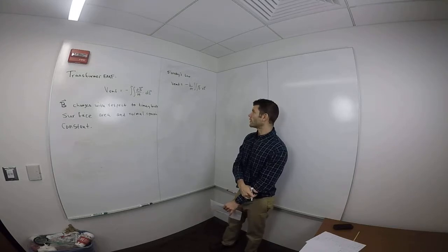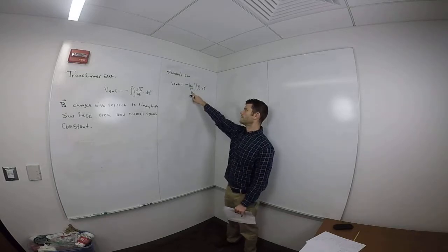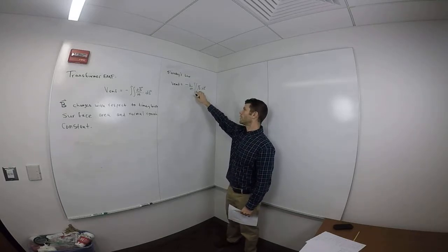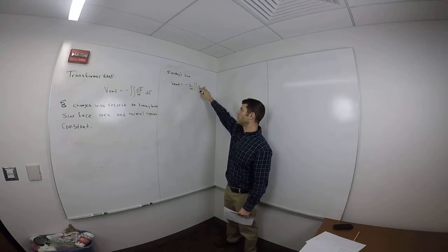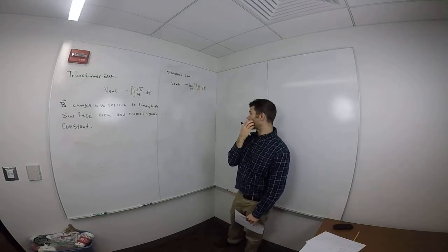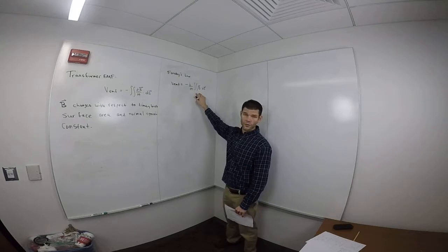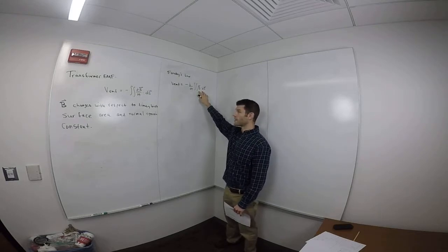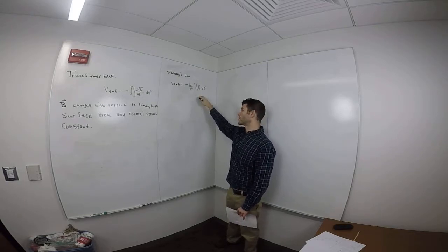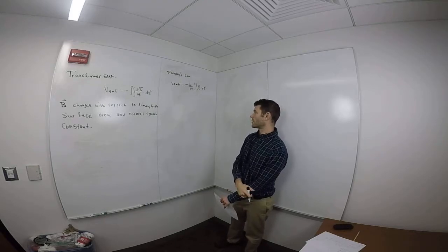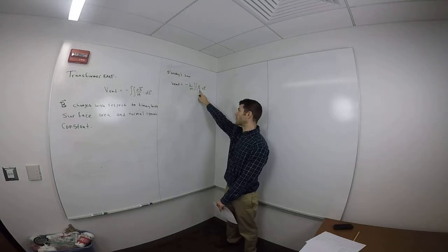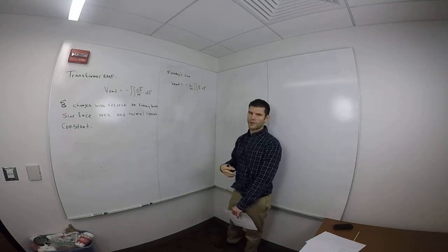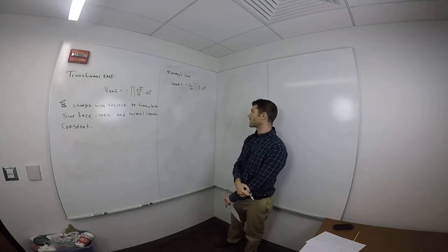All that this is saying is that this whole integral is going to give you some function which is time dependent. If this function changes with respect to time, we're going to induce a voltage. If this does not change with respect to time, we won't induce a voltage. So think about this. We have two different things there. We have B, which could change with respect to time, so the magnetic flux could change either in direction or in magnitude.